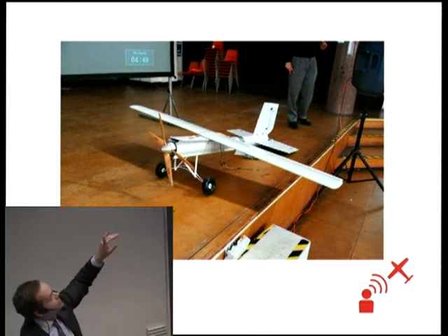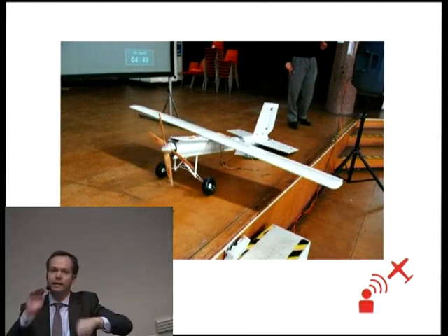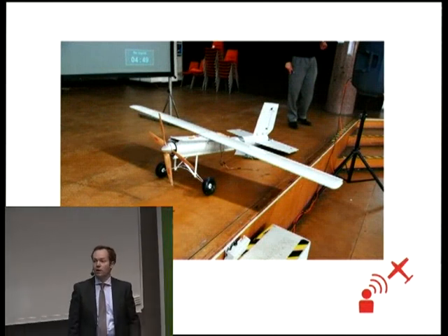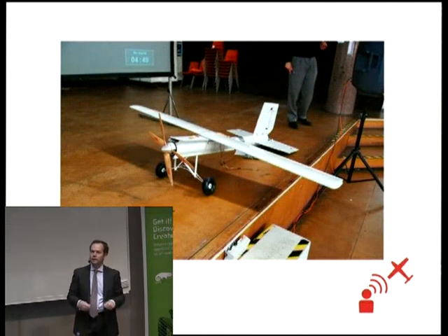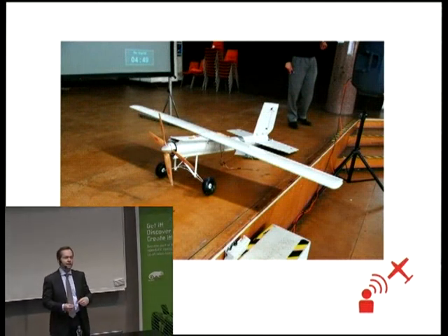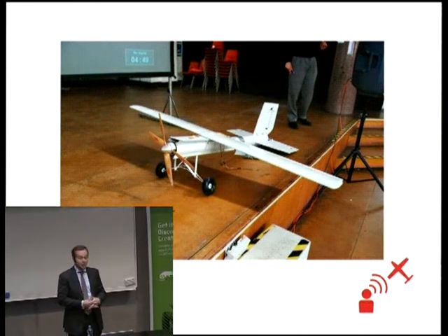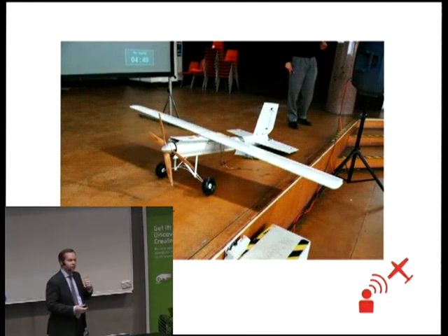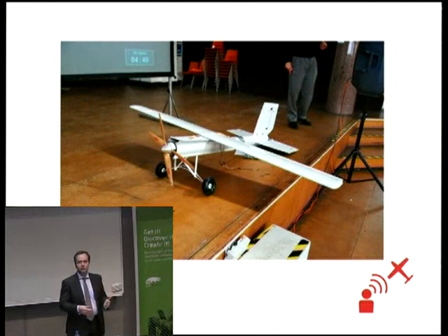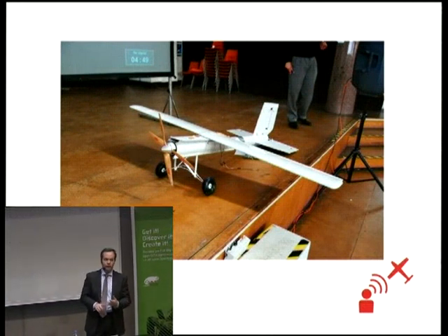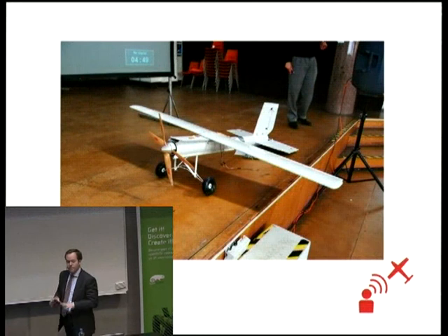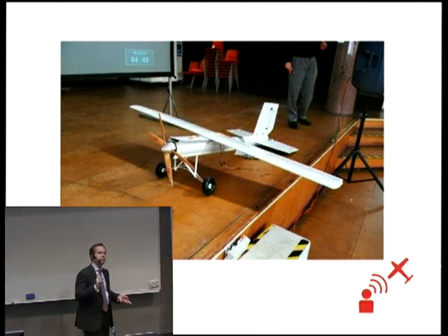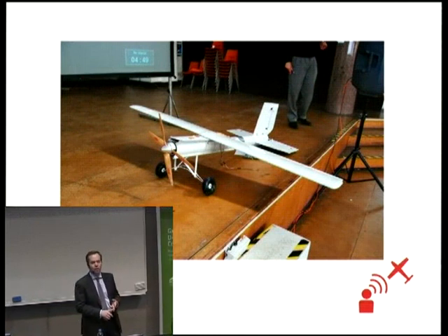We're going to have a very simple method to prevent the servos kicking each other out by having a slight zigzag in the wire, using the wire that the servos use. So even if they go slightly out of sync, they don't stress each other. In essence, what it means is this very simple airframe, which you can fly and rebuild if you have a hammer, a screwdriver, and a wrench. It has advanced features so that even if it loses servos, it doesn't go out of the sky. Even if you need to reconfigure it with a lot of weight, that's no problem.